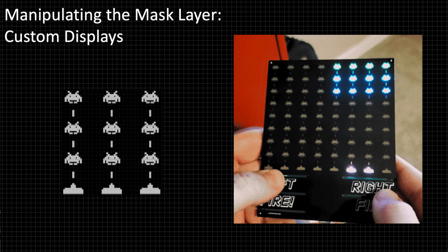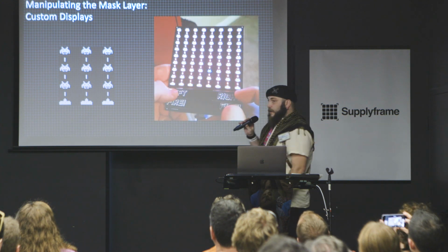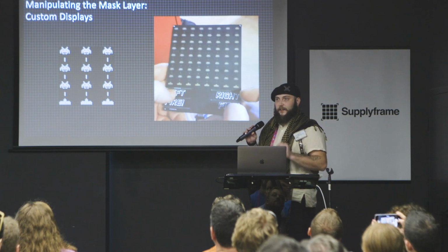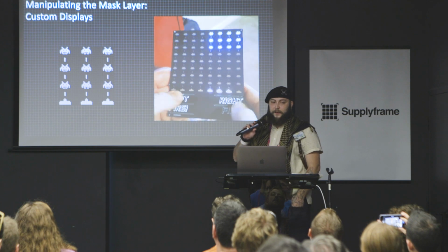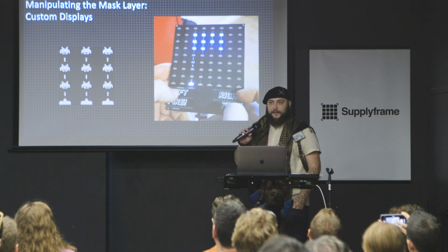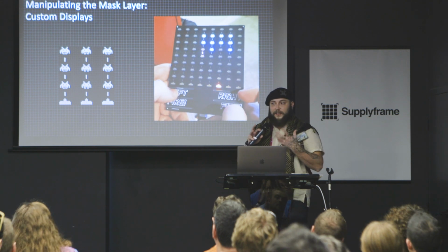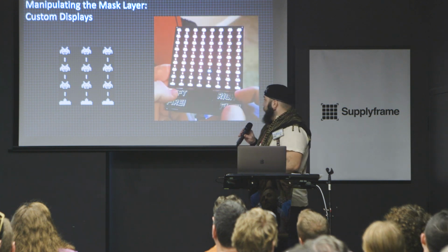So this is my Space Invaders badge. This is 3 layers of PCB with Space Invaders and little bullets all on the top layer. And underneath are just addressable LEDs. I'm using the APA102-2020 little tiny addressable LEDs. And what's running this is just an ATmega32U4. It doesn't take a lot of processing power if you have the addressables, right? It's because you're not maintaining a matrix of LEDs and having to keep them on long enough to see them. So this is a cool thing you could do.